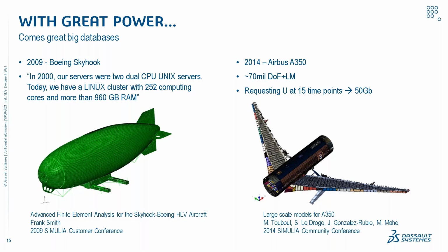So when you start getting to these large models, you really have to consider, how do I minimize the amount of data that goes into my final output database? Because you end up with a very large model. It may take a long time to load. It'll probably take a lot of space on disk, and trying to get that information shoved through the post-processor is going to be difficult.